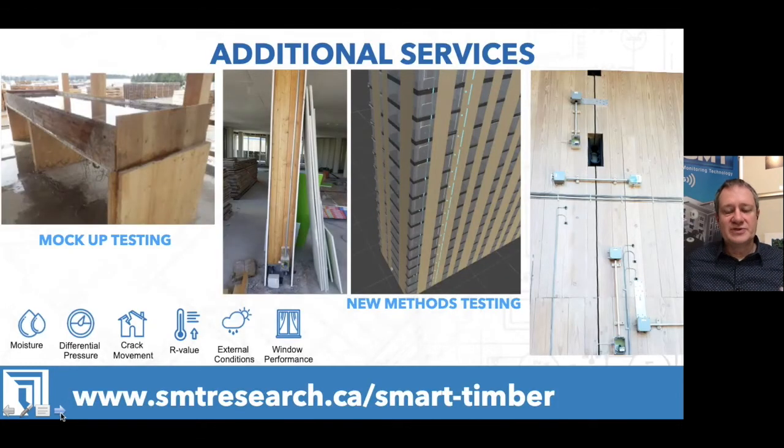A number of other services that we do with the mass timber industry are mock-up testing and validation of all sorts of different building science parameters. We work with projects like Brock Commons on floor-to-floor compression, monitoring the difference between the wood element versus the hybrid concrete stairwell, watching to see how much movement occurs over the construction period as well as long-term. And on the right-hand side, monitoring post-tension shear walls that are done in mass timber to look at their movement, again over short periods of time as well as long-term.